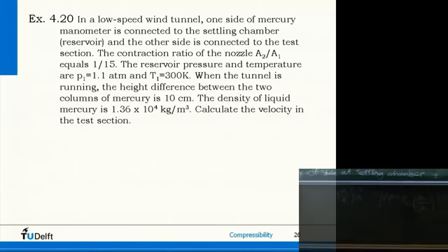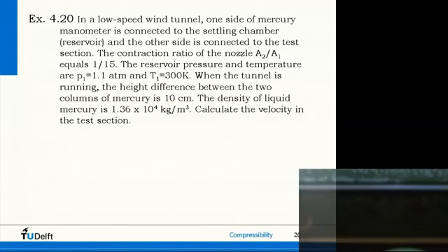Yeah? And that simple. So V2 is equal to P1 minus P2 divided by a half rho, so dividing by rho times 2, and then we have 1 minus A2 squared over A1 squared, square roots. Yeah? And this is how velocities are actually measured. So if you know pressure differences from manometers or pitot tubes, as I will explain in a minute, if you know contraction ratios, so areas, and somewhere a density for incompressible flow, you're there. You can apply this relation from Bernoulli and find it.